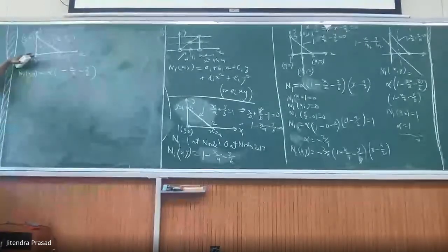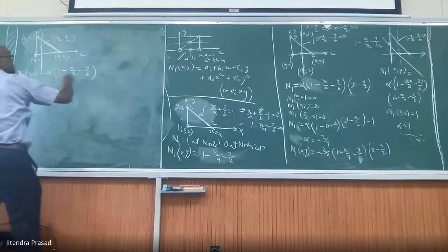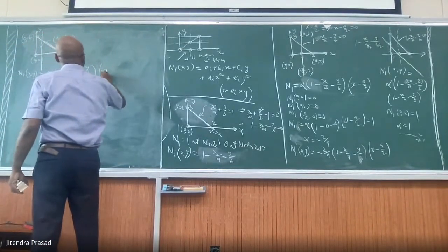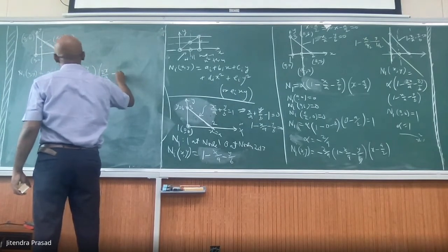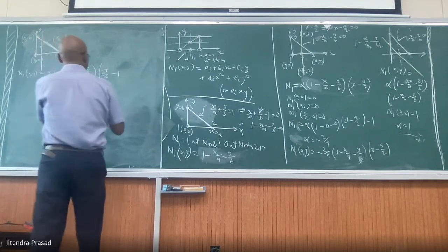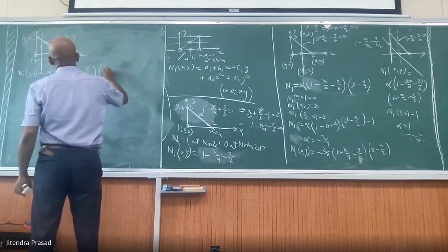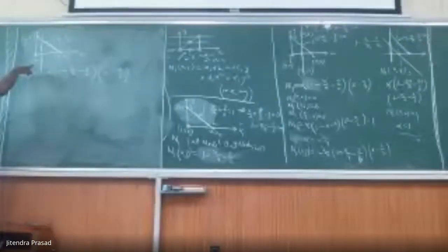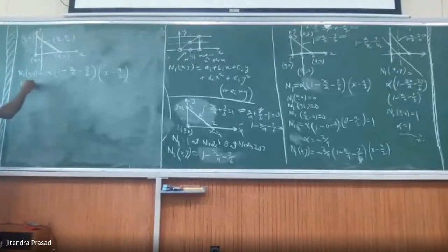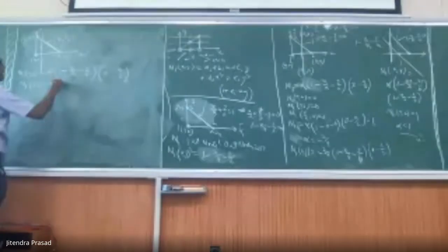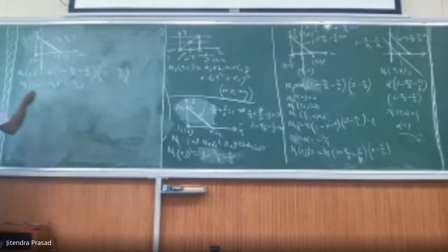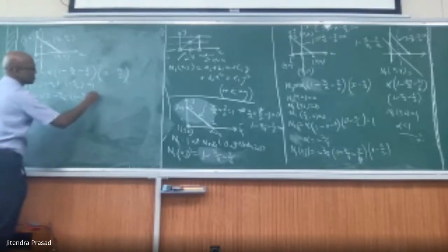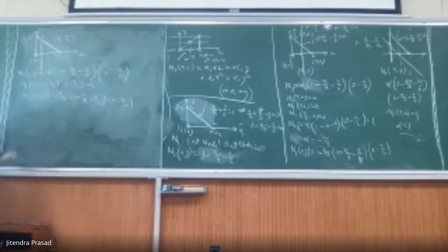So basically in this case, let us say we have the x squared term, and then we have this one. So we can write it as 2x over a minus 1, that is x minus 0, so x minus a over 2. And what is the value of alpha? Setting the value at 0, 0 equal to 1, alpha equals minus 2 over a. So alpha equals minus 2 over a, times 1 minus x over a minus y over b, times x minus a over 2. So our n1 is like this.